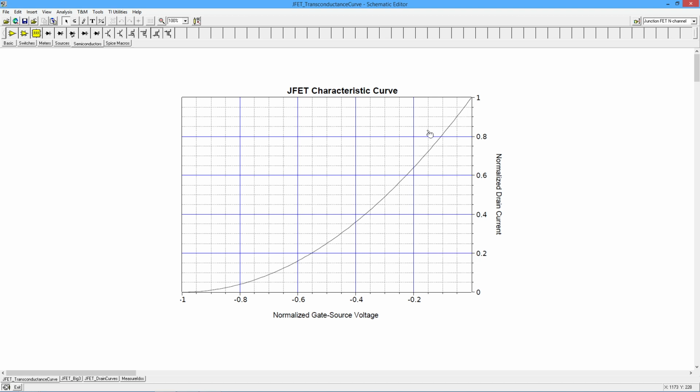So we need those parameters for things like DC bias. Like, for example, if I had a self-bias, I need another parameter. The third parameter, the biggie, is GM0, which is the transconductance at VGS equals 0. In other words, that's the slope right at this point up here. What's the slope of this curve? This is a current voltage characteristic, so the question is, what is the change in ID versus the change in VGS? That's the derivative or the slope of this line, and that's what the transconductance is. So GM0 is the slope at this point up here, which is basically IDSS,